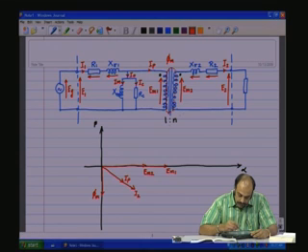Now, I2 is going to lag the induced voltage EM2 by the amount of lag which is produced by all the reactances, the impedances put together, that is the leakage, R2 and the load impedances put together. Now, this would be the portion of the phasor diagram that we had obtained for the ideal transformer.